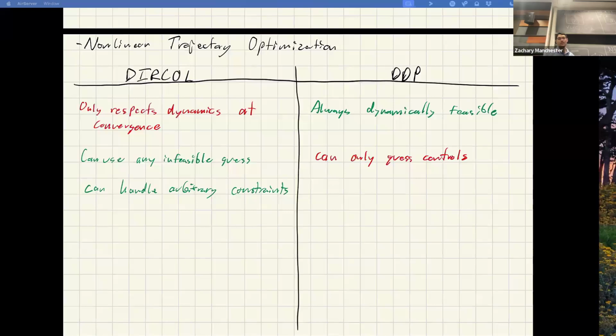another way of thinking about all this stuff is, basically what all these trajopt methods are doing, you can think about the whole thing as a big projection operator. The dynamics constraints are some manifold in trajectory space, and the cost function, if it's a quadratic cost in particular, is just a distance metric on trajectories, right? So if you have a quadratic cost and dynamics constraints, you're giving it an initial guess, some random trajectory that's off the manifold, and you're asking it to give you a dynamically feasible trajectory that's closest to that one under the cost metric, right? So it's very much like a projection.